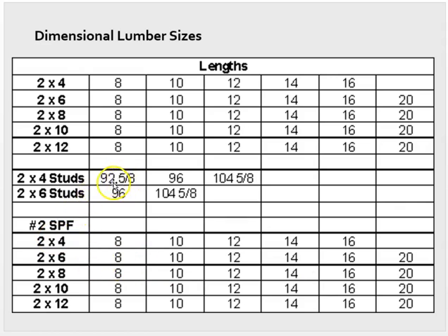And then just quickly to point out, which is important, is you could get pre-cut studs as well, and they come at various lengths. The idea is that this 92 and 5/8 would have a bottom sill and a double top sill on it, and we'll see images of that shortly. That would bring you up to the 96 inches, which is the 8 feet.